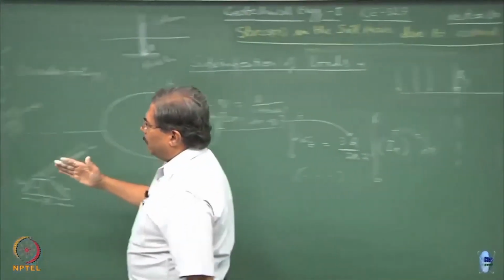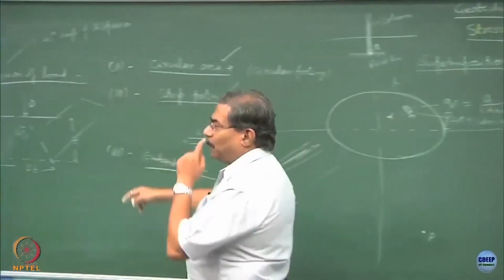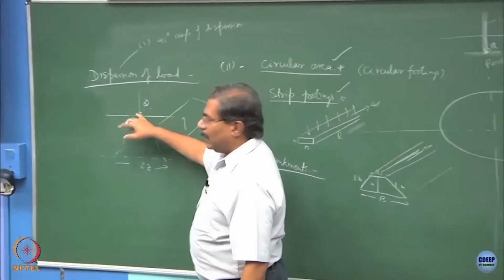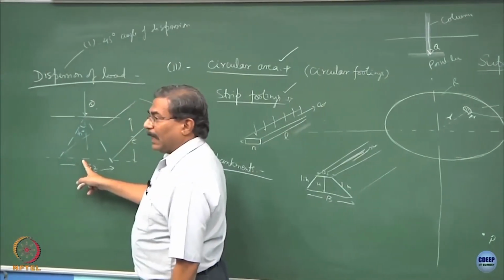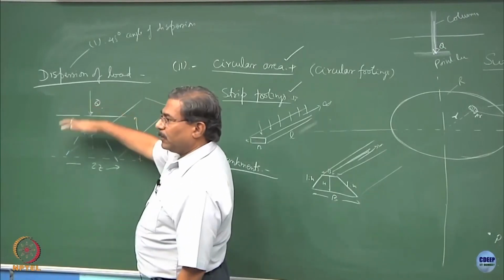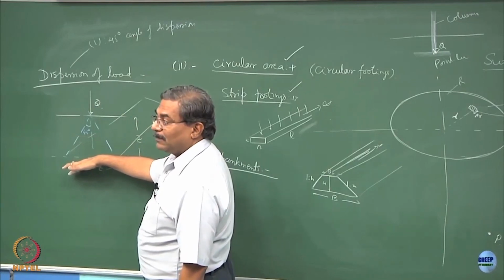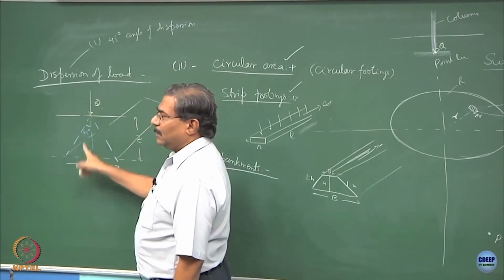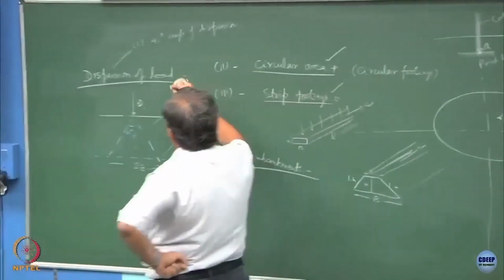What I have done is I have delegated the stresses from this point to this point. So when you design foundations, normally we give a foundation pad. What this does is give me 2-3 advantages. I have created a pad for the foundation system and I have reduced the stresses. This is engineering.